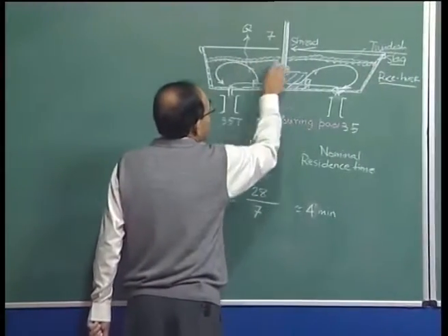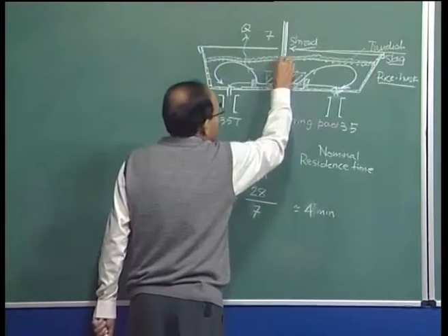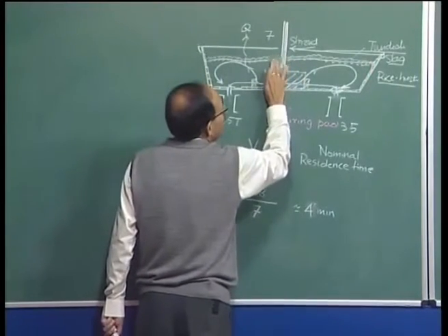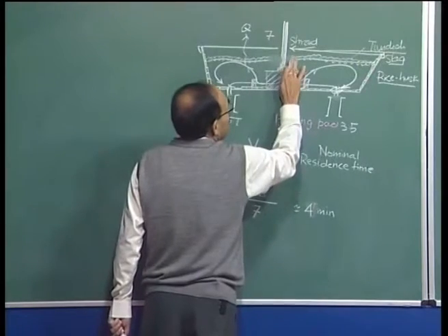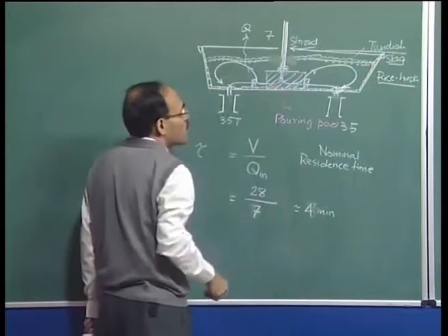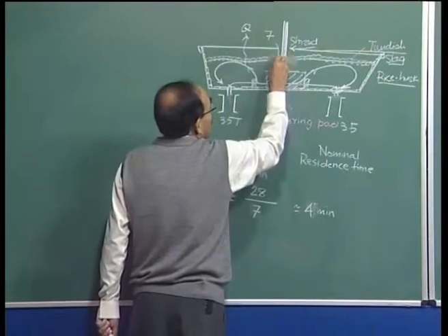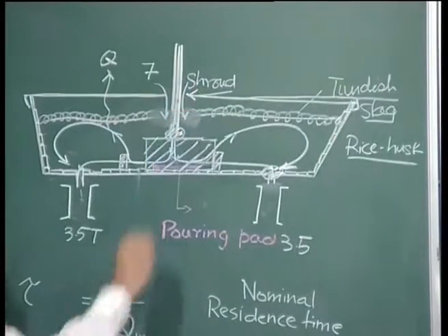So, the turbulence is not very good here, and we must also know that we have a lot of slag here. So, if we have a lot of turbulence activity here, what is going to happen? This area is going to be opened up because of the tremendous amount of turbulence present. So, therefore, we can see that through this there is a lot of reoxidation.